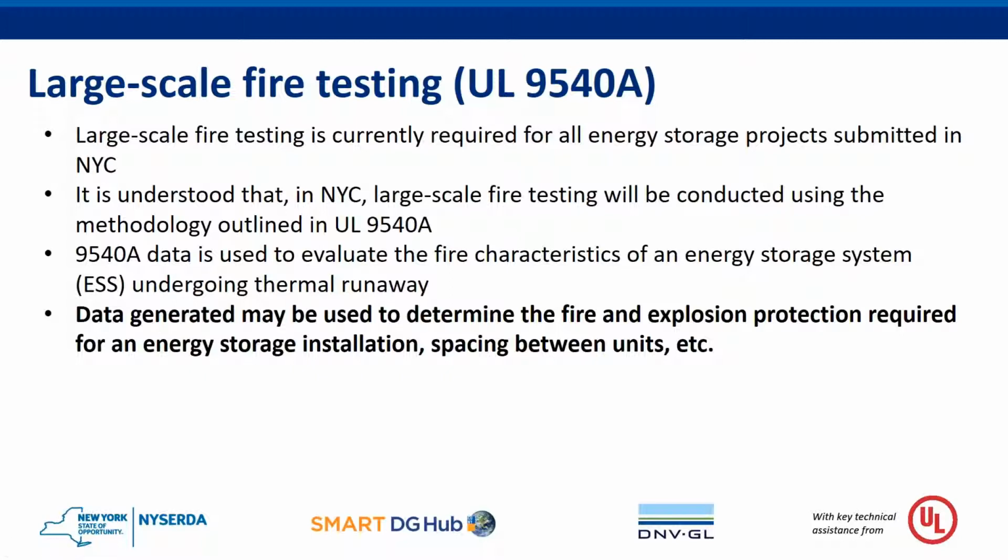Large-scale fire testing is currently being required for all energy storage projects submitted in New York City. It's understood that in New York City, large-scale fire testing will be conducted using the methodology outlined in UL 9540A. Now, this data can be used to evaluate the fire characteristics of an energy storage system undergoing thermal runaway, and then used to determine the fire and explosion protection required for an energy storage system, such as spacing between units, ventilation sizing, etc. Go to the next slide.